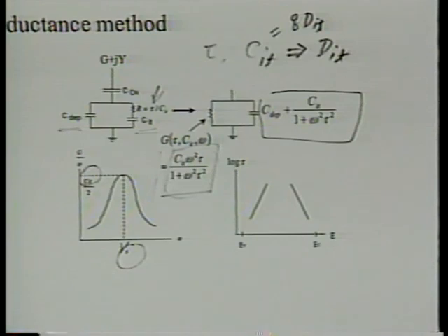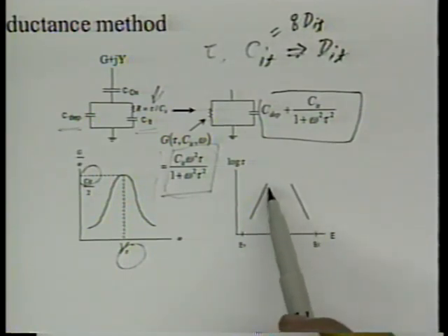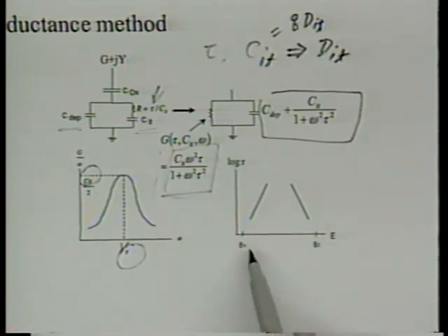Do you see how this works? All right. So it's very straightforward. And if you do that, you will be able to find, for example, tau indeed tends to be long near the band edge, and often this data is not even complete because this number may be too long for this technique to work comfortably. It will require measurement at very low frequency. We all know that RLC meters have limitations when you make measurements at too low frequency. But typically what's noticed is an exponential relationship between the time constant and the energy of the traps. This is a very nice technique, but for some reason it's not very often used. I think it's a somewhat underused technique to characterize the interface.